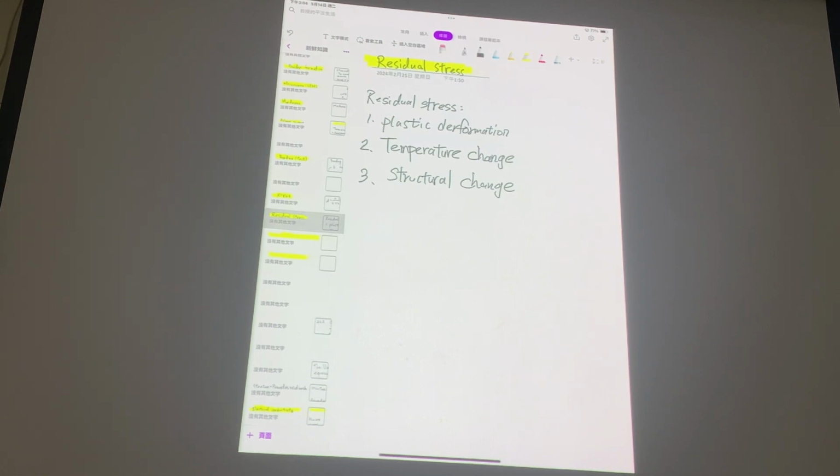By the way, through X-ray, you are able to detect residual stresses. And I also have the equation here. But actually, on the second block, I'm not going to write the equation because when you use X-ray to do residual stresses, you have to be very cautious, because there are other factors that influence.